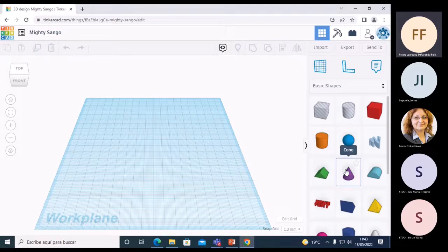With the components, we can use Boolean operators, and we can create more complex objects. In TinkerCAD, the union and the difference of the objects are supported. That is the way to create this one. And the common part of the objects is not definitely defined. So it can be created, but it is a very complex idea how to create them. So the suggestion is to avoid the common part of the objects. Okay, design the other way.